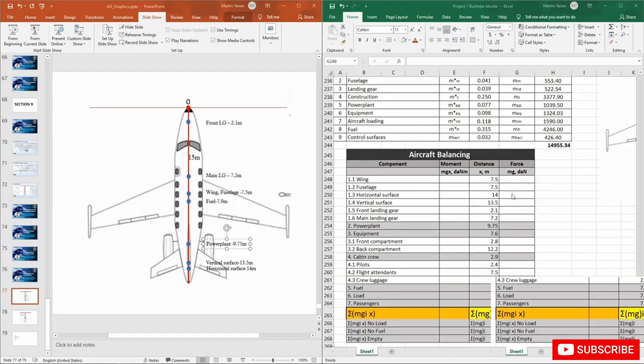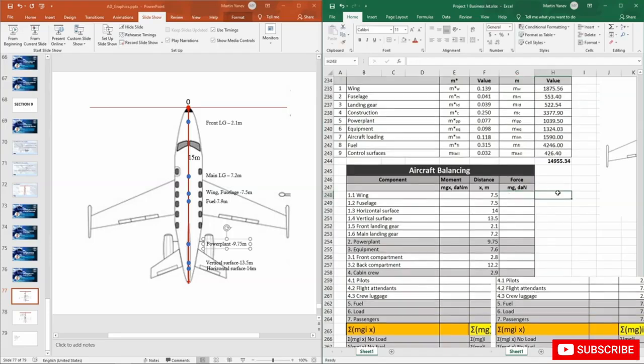So here I'll first estimate the forces. And as we don't want our forces estimated in Newton, but in daN, everything will need to be multiplied by 0.1. Actually, you know what I'm going to do, which is going to be quite fast. In this cell, I'll write equal to 9.81, which is the Earth acceleration, multiplied by 0.1. And then each cell here we're going to estimate with this one, and I will show how this is done.